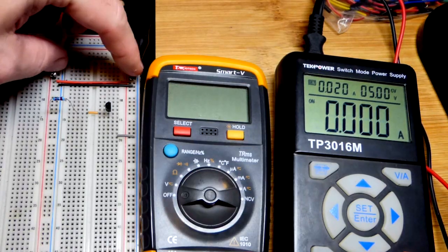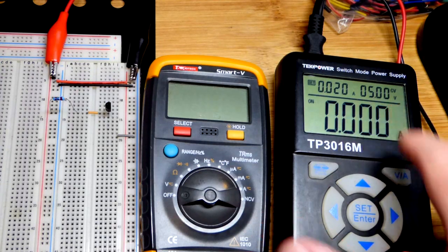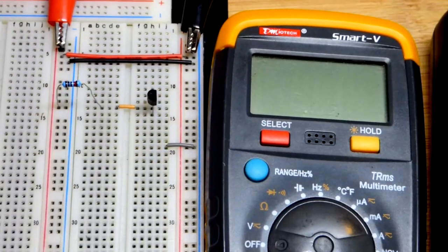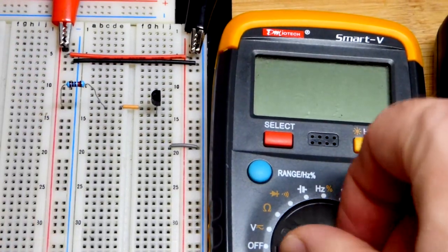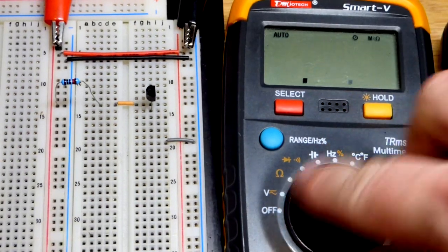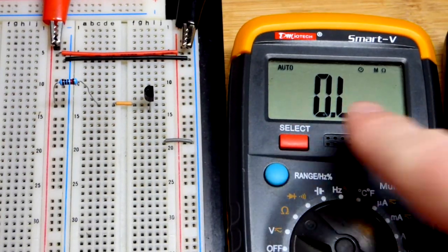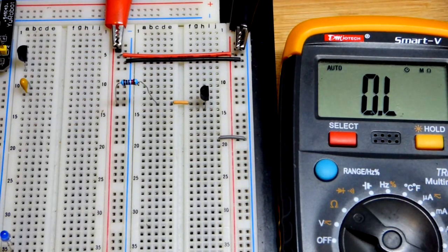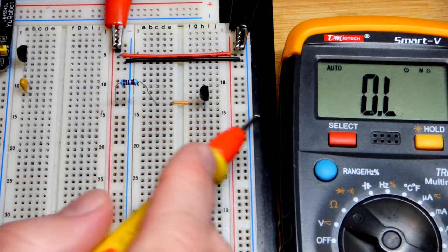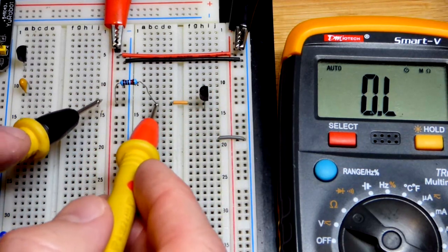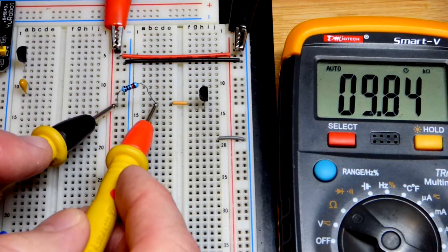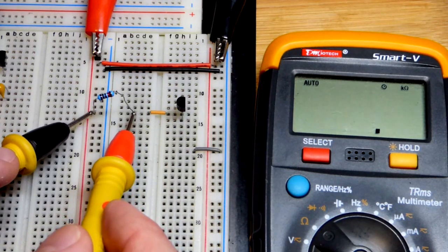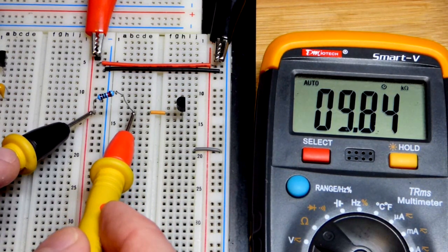Now I have the power applied, the power supply at 5 volts. It's not providing any current now. I move the transistor up and connect the resistor to the base. Let's do a quick resistance measurement. You can see the ohm symbol. This is an auto ranging meter. For the vast majority of things, it just auto ranges. You just have to tell it what you want to measure, and it does the rest. The transistor does not go to any side of the power supply, so the resistor is not being powered. We can measure the resistance right now, and it's just shy of 10K, 10,000. That's kilo ohms in the top right symbol.